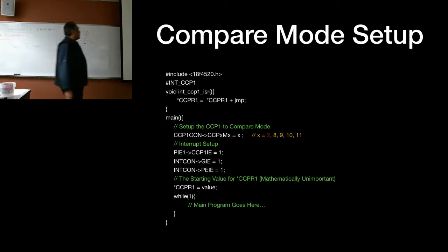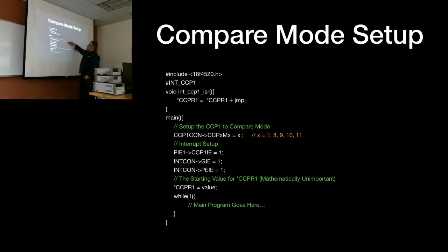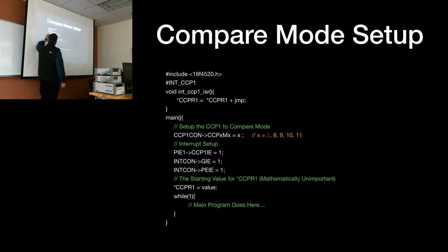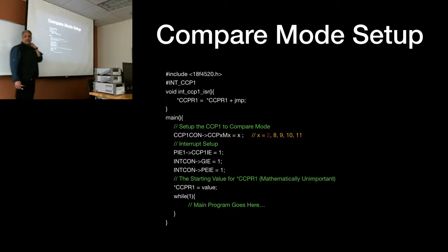So here's the change in code. The code looks exactly the same way. There's your CCP, there are your 3 values, there's a timer 1 that we forgot in here again. There is your starting value. Once again, the starting value really does not matter. The only reason, and I think this is more intermediate level programming, you don't have to remember this. The reason why sometimes we have a starting value is because I want to synchronize this with something else. So when it comes to synchronizing, I can choose my starting point so that I can get my circuits synchronized. But in general terms, what matters is this instruction up here. The value that shows up in that plus sign will determine how often the circuit will interrupt. See that?